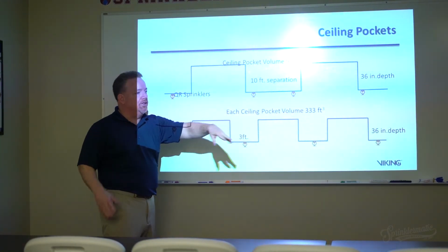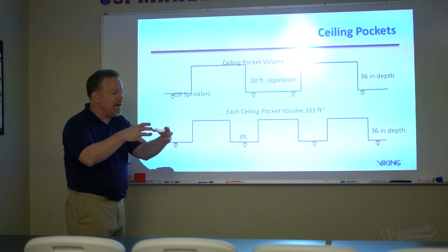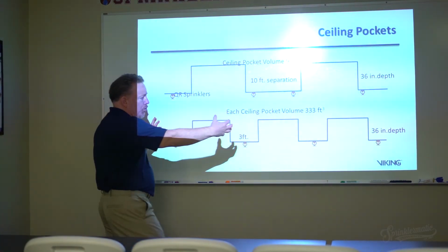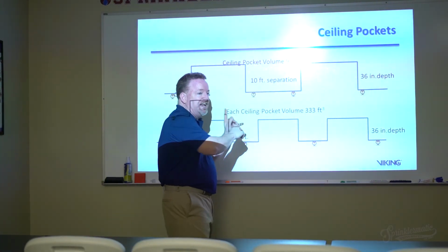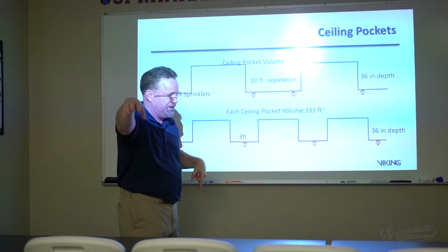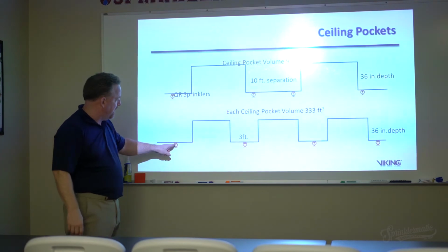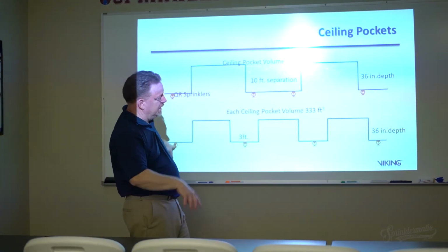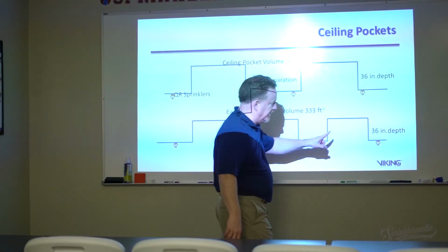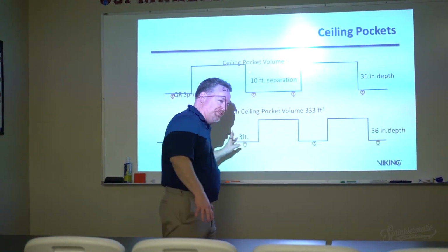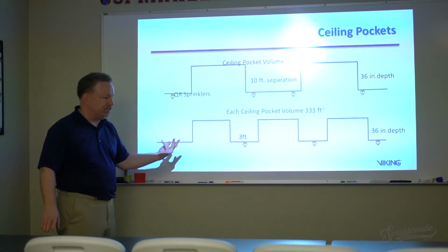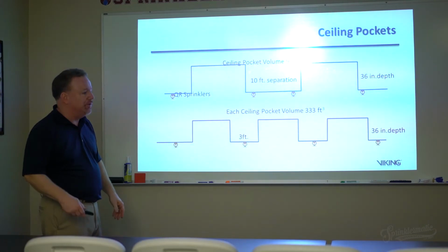The accumulation of those three in one area is permitted, as long as this whole accumulation of three is now 10 feet from the next accumulation of three. And you have to have a sprinkler head on each down projection? Well, you have to have your spacing. Correct. Now, just for showing it, we put sprinklers in each one, but you might not need to do that.